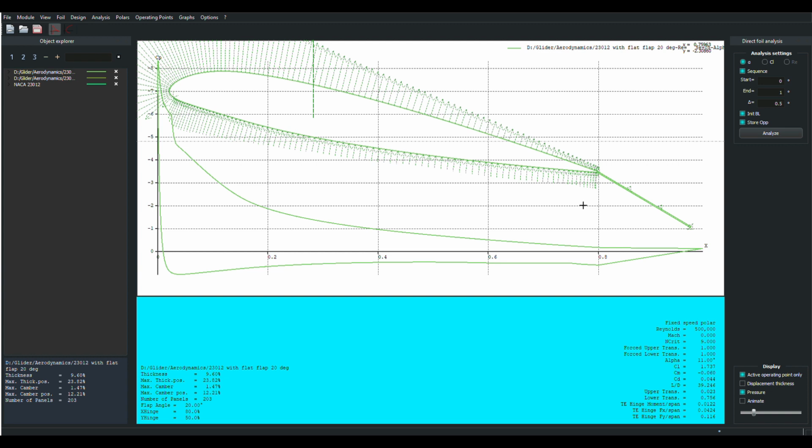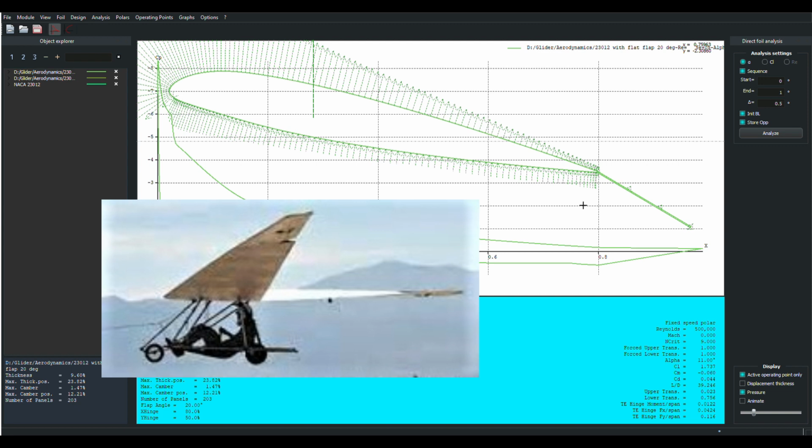And so we have 6 aircraft designs that have arrived at this conclusion, not by understanding the aerodynamics, but by meeting the demands of transportability. Because we want them to be transportable, we have to take the elevons off or fold them up somehow. We ended up with essentially flat plate elevons that are tacked onto the trailing edge of an airfoil. And that turns out to be the workable answer. And nobody else has tried, as far as I know, a foot launch aircraft with elevons with the bull nose leading edge and tried to foot launch it and fly it at really low velocities.